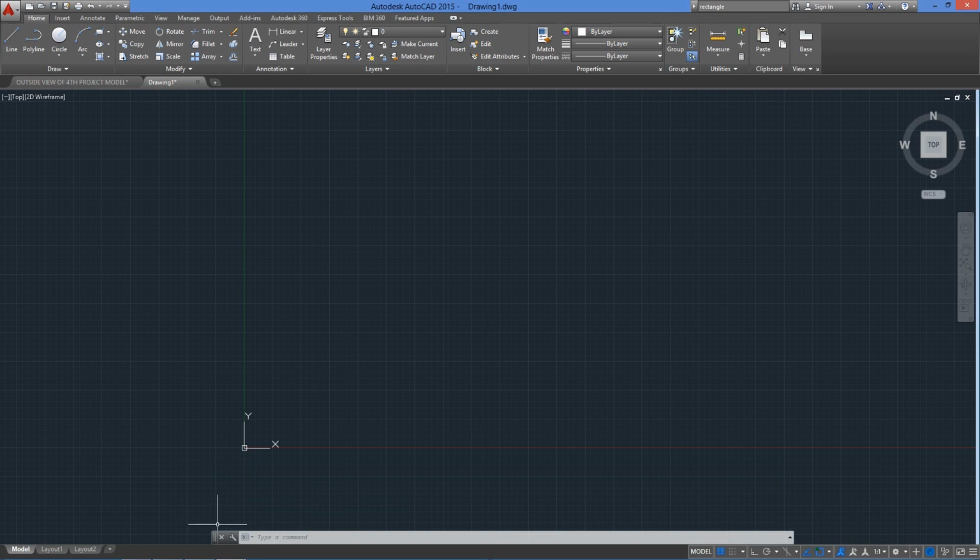We can enter here directly our command selection by typing the command or its shortcut, and it will suggest options as we type. For example, if I click on it and start typing REC, it provides a set of possible options to choose from, so I can select rectangle command. Now, without clicking on it, the same is true, but instead of on the command line, it will be on the tooltip. You can see it here.